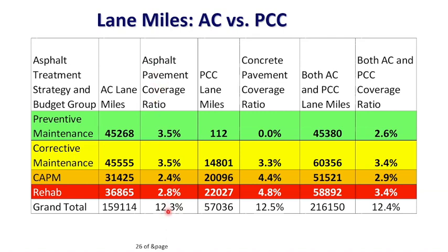And AC pavement, every year we are doing about 12.3% of our total length mile. That means almost every 8 years I cover my entire network once, no matter if I paint it thin, with only one layer, or I do a thick overlay. That's for AC pavement. Now let's see for PCC.